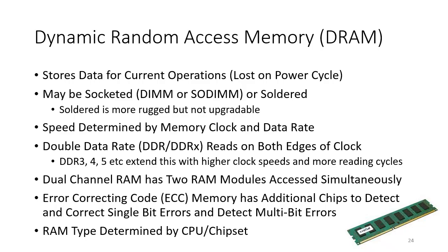And I would say for industrial applications, pretty much mandatory to have ECC memory. In other applications, it maybe doesn't require that much. I mean, we're talking about very, very small numbers of errors. But in industrial applications where they could cause issues, ECC memory can help us overcome those errors, or at least detect them and avoid operating on invalid combinations of values.